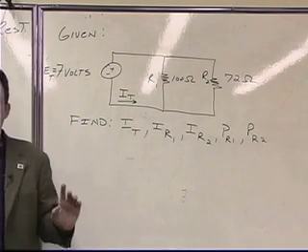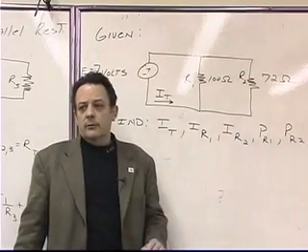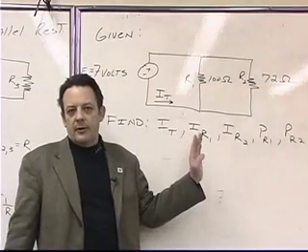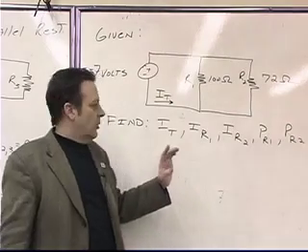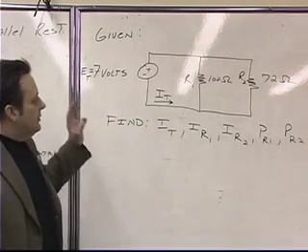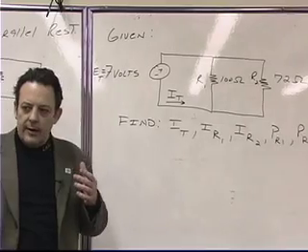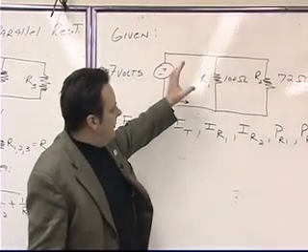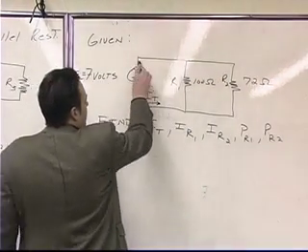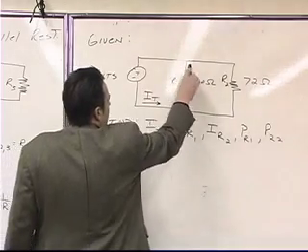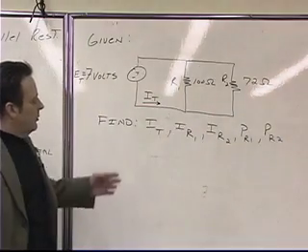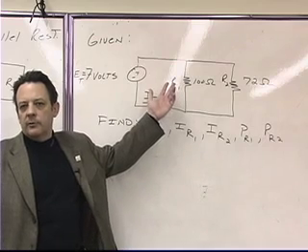Now, there are several different ways to solve this circuit. There's not only one way to do it, and we don't always have to start with the first thing we're asked. In other words, we don't necessarily have to go from left to right as long as we get everything. Now, as I look at this circuit, one thing that jumps out at me is that I have two loads connected in parallel. If I look at these loops right here, there's only two things in each one of the loops. So by inspection, what's the voltage drop across resistor number 2, resistor number 1?